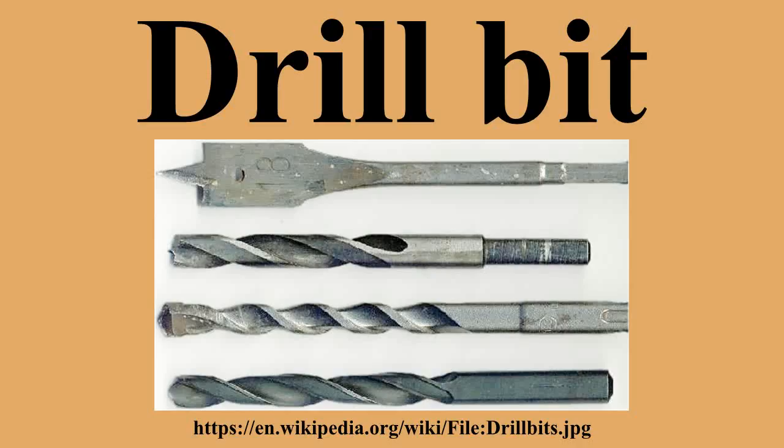Step drill bits. A step drill bit is a drill bit that has the tip ground down to a different diameter. The transition between this ground diameter and the original diameter is either straight to form a counterbore, or angled to form a countersink. The advantage to this style is that both diameters have the same flute characteristics, which keeps the bit from clogging when drilling in softer materials, such as aluminum. In contrast, a drill bit with a slip-on collar does not have the same benefit.